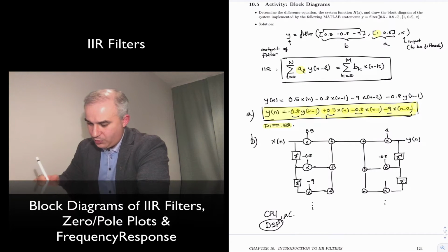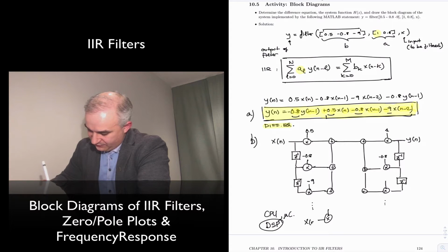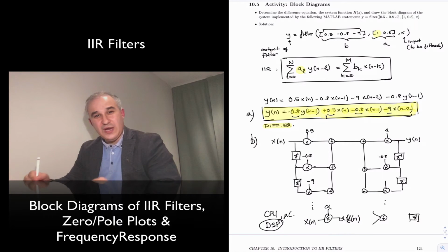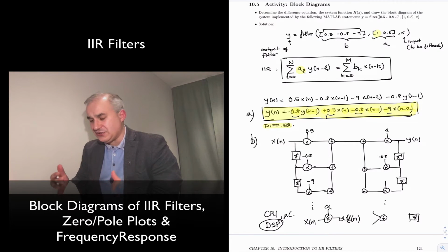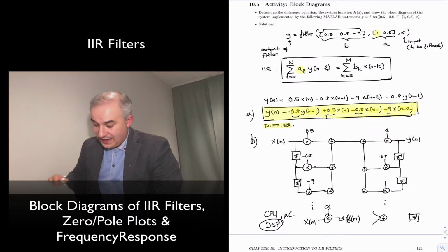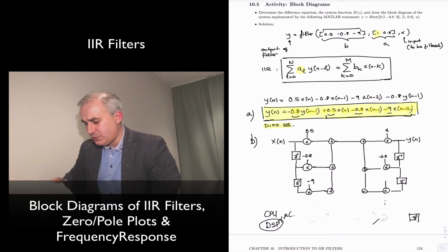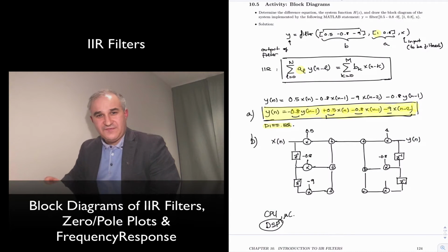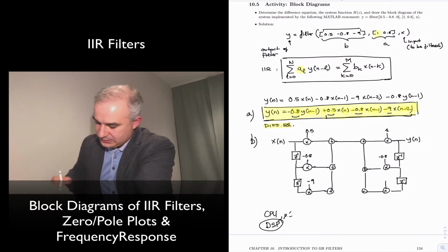Over here, all we are doing is making sure that we implement these multipliers, x of n plus some value, the others, and the delays really efficiently, to do several billions of these per second. And that's because that's what you need for filtering, that's what you need for the FFT. It turns out that all this stuff you can implement with the fast Fourier transform. Okay, you can do fast convolution using the fast Fourier transform, as we will see.